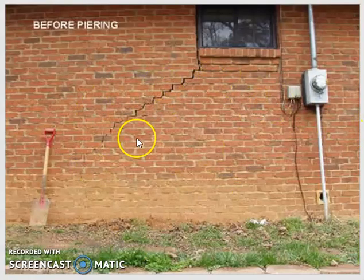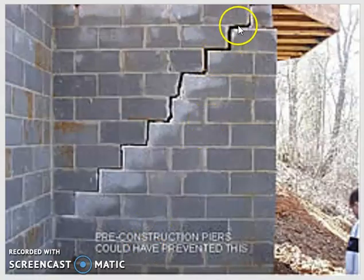If the structure is stable but starts to suffer from excessive settlement, typically you start to see a lot of cracks forming, and the cracks are often diagonal. Diagonal because the settlement is uneven. We call it differential settlement. That is, some places settle more than other places, so there is a difference in the settlement. Also, you can see here the diagonal crack forming. Another example, you can see quite a wide crack forming at the top here, because this part here is settling more than this part.